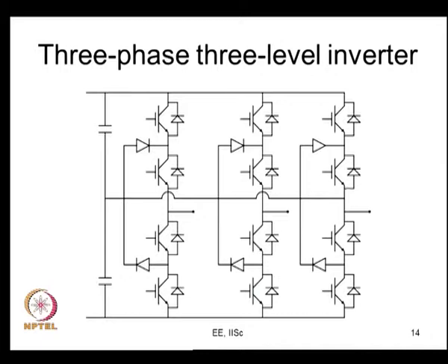Now, remember all the space vector PWM ideas are actually valid for 3 phase cases and not really for single phase. For single phase inverter also we discussed some PWM, we looked at some even harmonic injection also in one of our lectures in the triangle comparison based PWM. In that module we discussed one. All the space vector PWM idea and all the third harmonic injection, common mode injection are all ideas which are actually applicable to 3 phase. In fact, they are extendable to 5 phase, 7 phase, etc. also. Alright. So, this is the inverter that we are actually looking at.